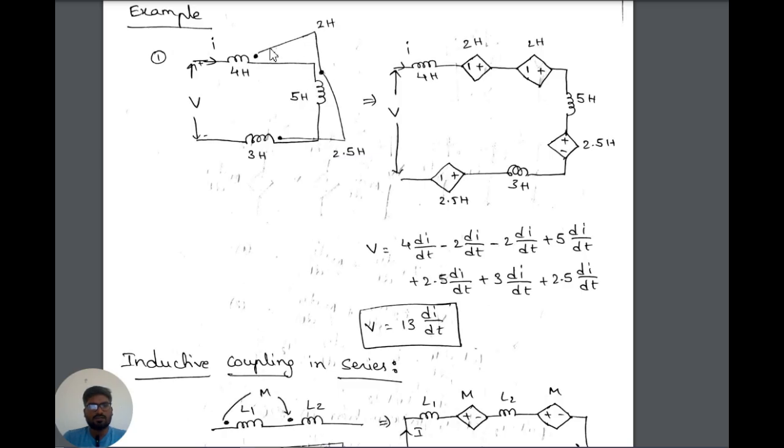So first we will write with 4 Henry. So the mutual inductance caused by current in the 4 Henry is, as the current leaving the dot, so this starting point will be negatively assigned and next will be positively assigned. So it is negative and positive. This is self-inductance as it is 5 Henry, and this mutual inductance here is linking with the 3 Henry.